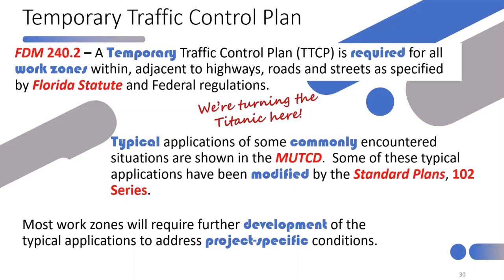So think back to what I've been talking about with borrowing the idea of nominal compliance and substantive compliance from the HSM. The direct application of a standard plan to every situation is not actually going to be substantively compliant at all, because it says here most work zones. I would suggest to you that maybe more than most, nearly all work zones are going to require some degree of additional development of those standard plan details, because you have to address project-specific conditions.